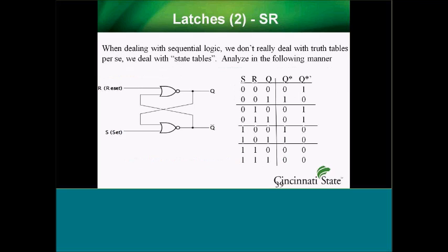So I said, okay, let's really line up how this works. Let's take S and R. Let's take Q. Let's go ahead and set Q, which is our state, and then we're going to put in these inputs, S and R. Notice that the latch is exactly what I just drew in those larger slides. The next state of Q depends on what Q already is, because it's being fed back into the system as an input, and so is the inverse of Q, in addition to new inputs R and S coming in.